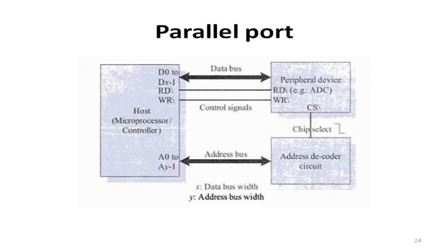Depending on how many bit address, that many address lines are required, and how many bit of data, that many data bus is required, and two more control signals, that is read and write signals, are required. So whether to write into the slave device or whether to read from the slave device.